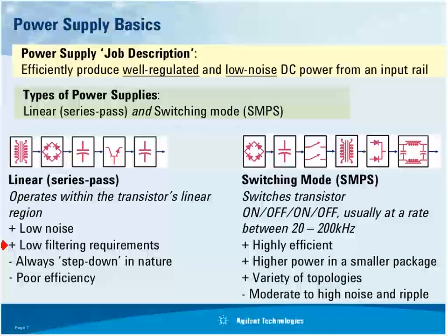However, they're only step-down in nature, so you can't take a given input voltage and step it up to a higher voltage. It's always step down. But this is the biggest drawback: they're very inefficient. We could add a few more negatives. They're more expensive, they're heavy, and they can generate a lot of wasted heat if they're not very efficient. Most products today have switching power supplies in them, as I mentioned earlier, often called switch mode power supplies, SMPS. The technology, and we'll talk a little bit more about this, although this is not the focus. We're not going to get into the theory of designing power supplies.